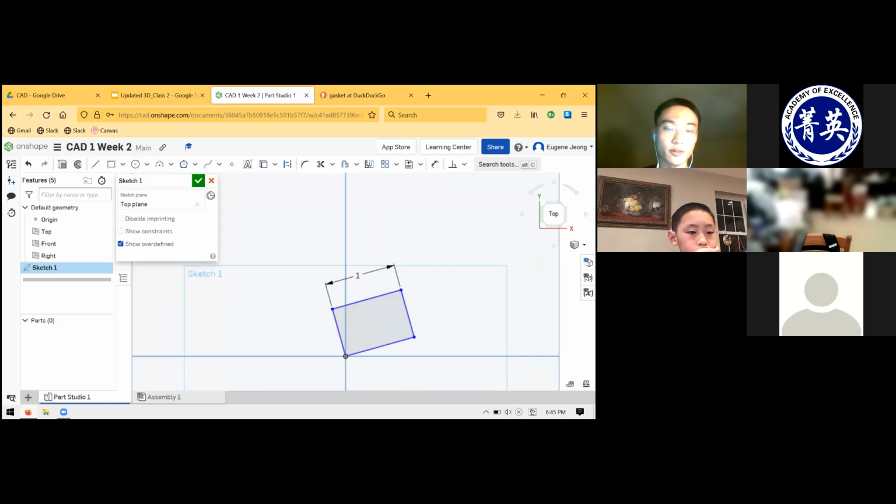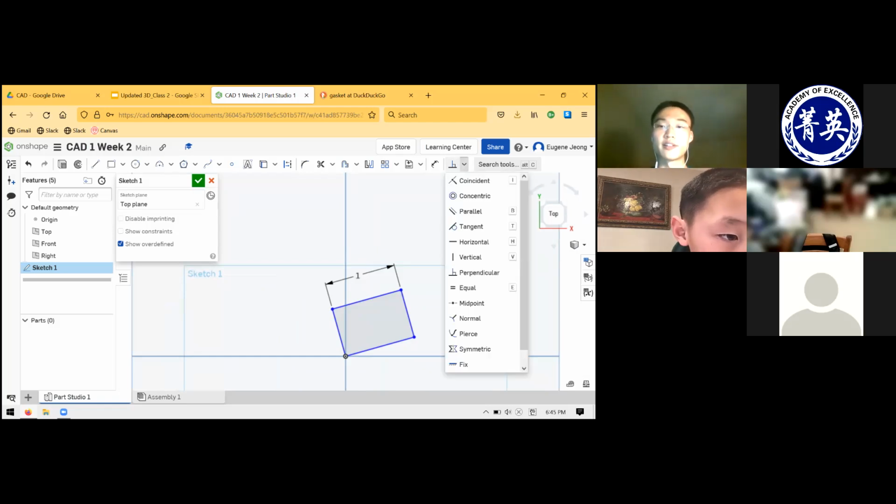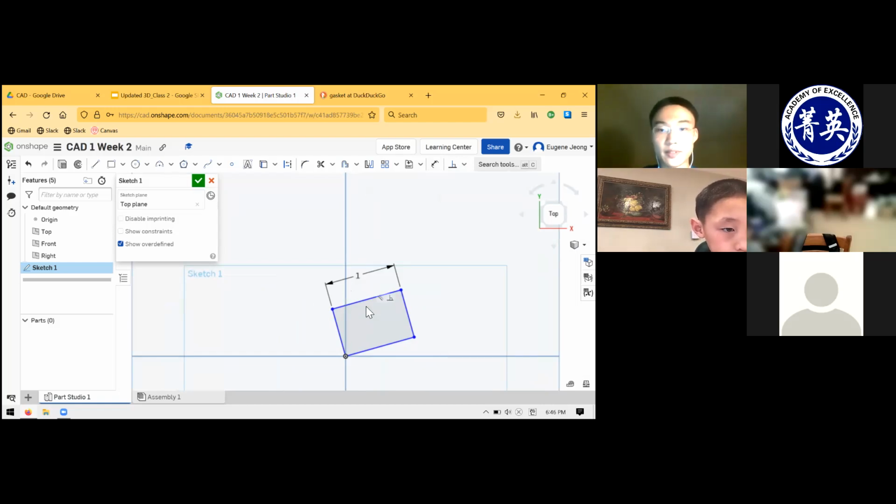So dimension, it's a lot like a relation. It's just that instead of these geometric relationships like parallel or perpendicular or coincident that we talked about, it's just a number. It forces a number onto your parameter, right? Your entity. So that's the first one. I'll show that again and do the other one.